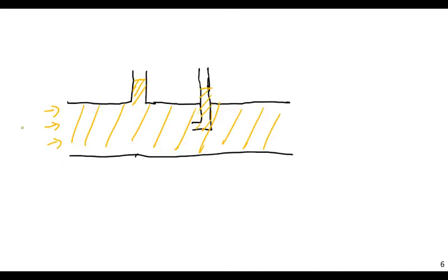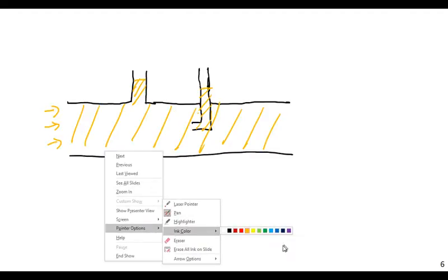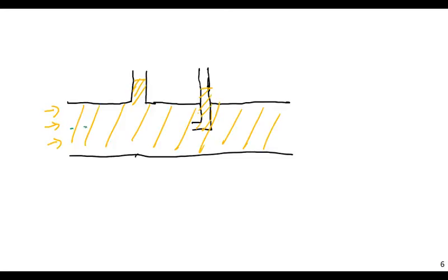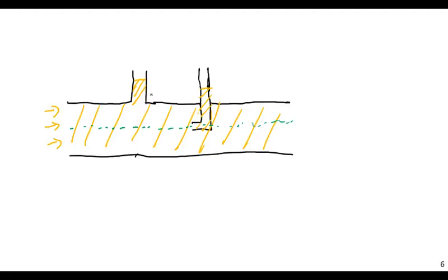So there's going to be a certain velocity, and here's the center line of the pipe. And something interesting happens here. What conditions are needed for this to occur? Well, the reason I have these two different tubes is that they are going to react with the fluid differently. This simple vertical tube is not exposed to the velocity of the fluid. It is merely exposed to the hydrostatic pressure of the fluid.